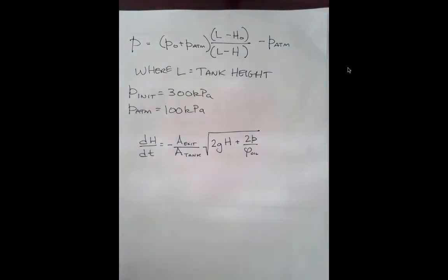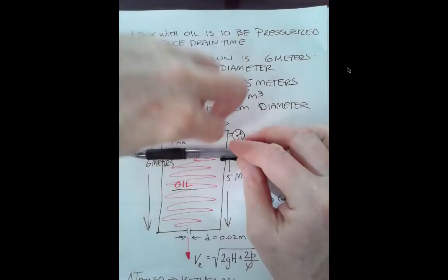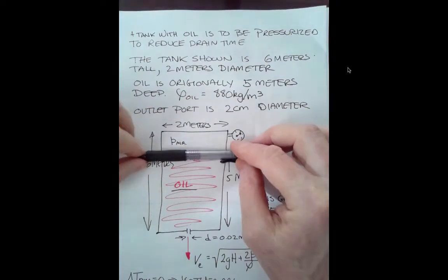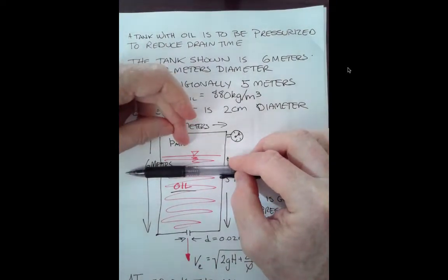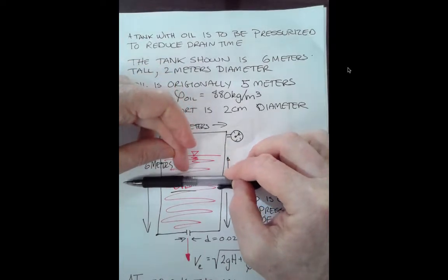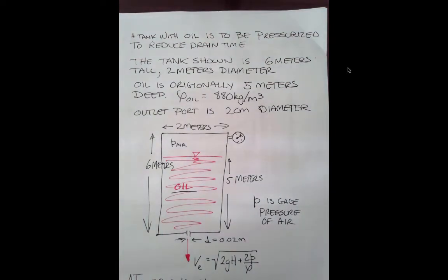So as this tank drains, what's my tank? There it is. Come back here, tank. Okay, so we pressurize this, open a valve, and this starts to drain. We're not adding additional air in here, so the pressure is going to go down as the tank drains. It's still above atmospheric, so it's not going to draw a suction and then stop draining. So we want to see how much oil we can get out of this tank over a 1 hour drainage interval.